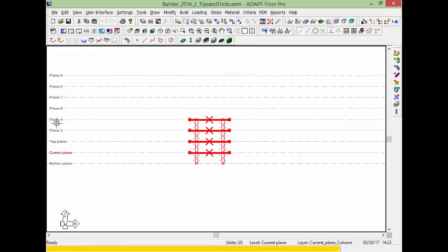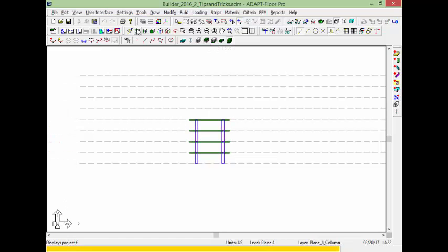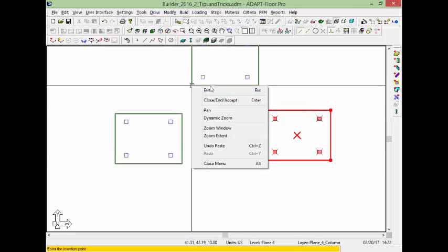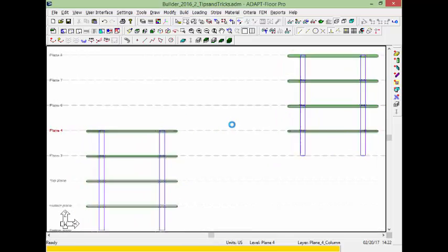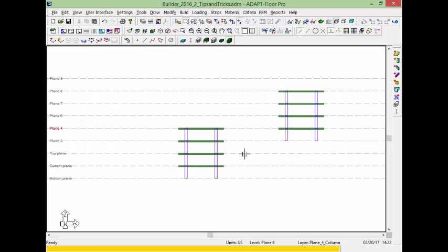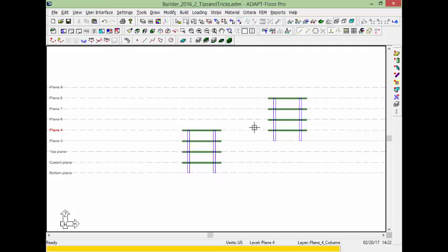and in this case I'm going to use plane 4 as my insertion plane. So we'll go back up to plane 4. I'll go back into plan view to Control C, Control V. Because current was our reference, plane 4 is our insertion. This plane here maps to this plane, and then we have the vertical stack which fits within the additional planes that we had created. Therefore, we have a replicate of the four stories and the associated components in this new copy.